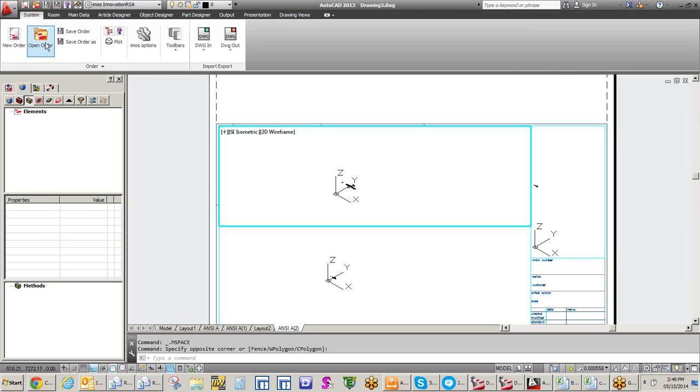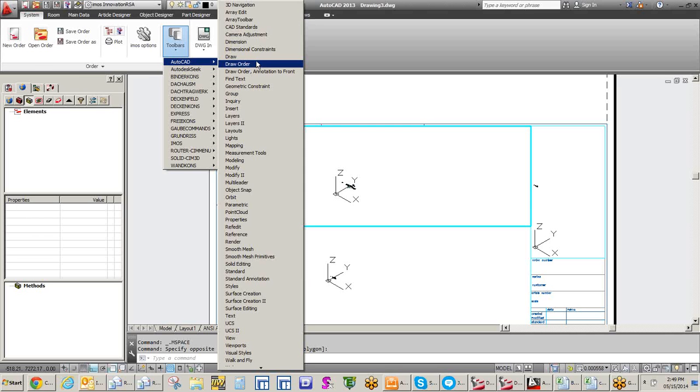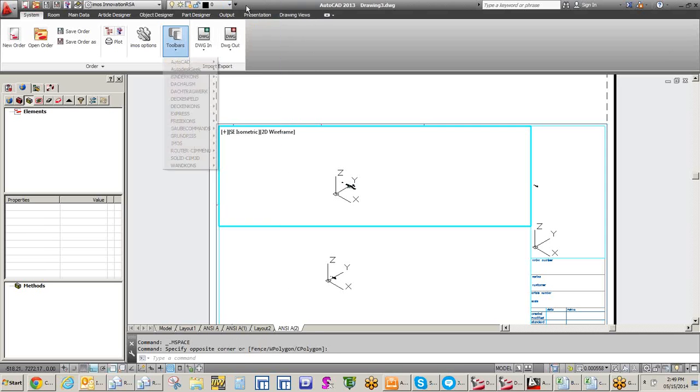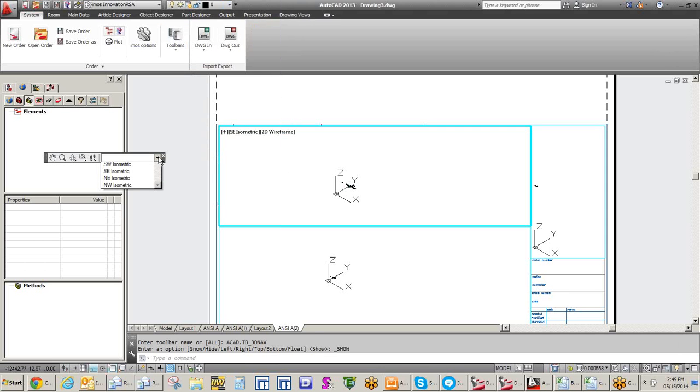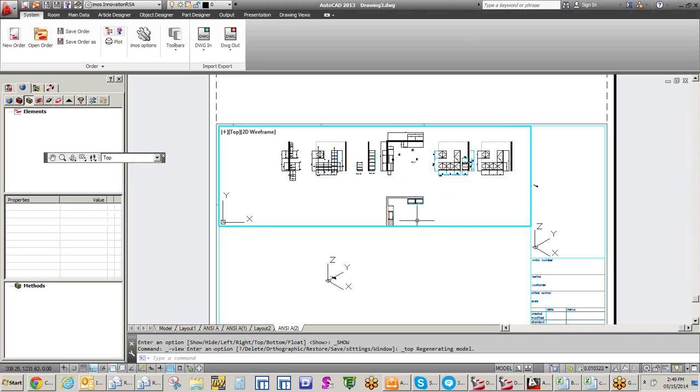I think, Roger, you basically would put whatever you want into what view, and then you would use AutoCAD's dimensioning tools, dimension horizontal, vertical, whatever, continuous, baseline, and you're going to pick and select each and every dimension that you want to have. So it's a laborious process, no doubt. Yeah, so we're pretending this is the only thing that we've got.